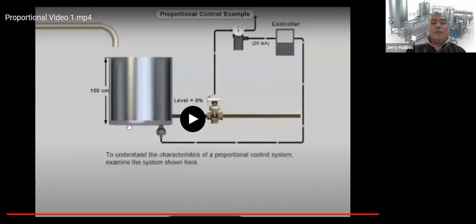So the point here is that if you increase the proportional gain KP, the output is higher compared to 1, and it reaches your desired output or set point faster. The valve is closed at 100%, considering the tank is still empty. It only executes a 4 to 20 milliamp signal, if you remember the formula from the last time in Process Control 1, Process Automation 1, rather Instrumentation 1: your 4 is 0%, and your 20 is 100%.